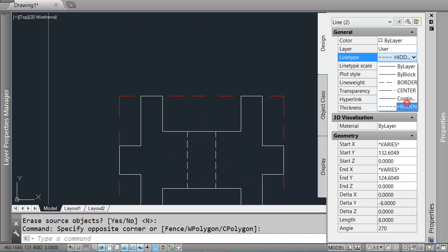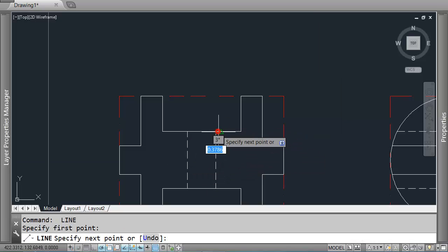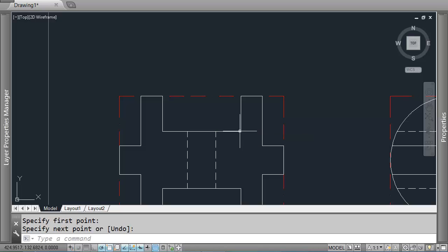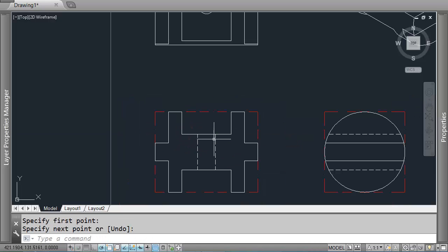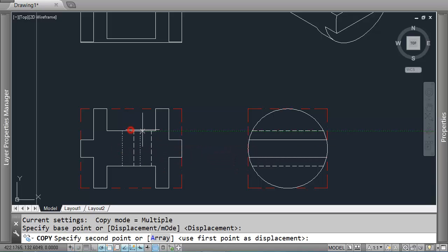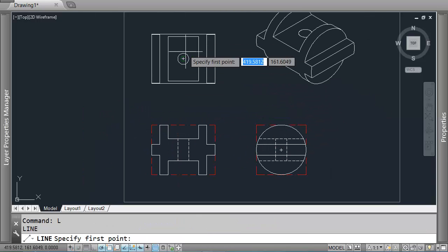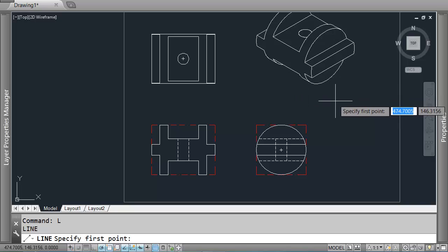That's a hidden line for that one. Double check that that width came out okay. All of these lengths should be whole units, 3.5 or half integers. That's okay. I can even save myself a bit of time and copy this, because the spacing on the whole is going to be the same. Copy that across. And last thing I need is the center lines on this shape.